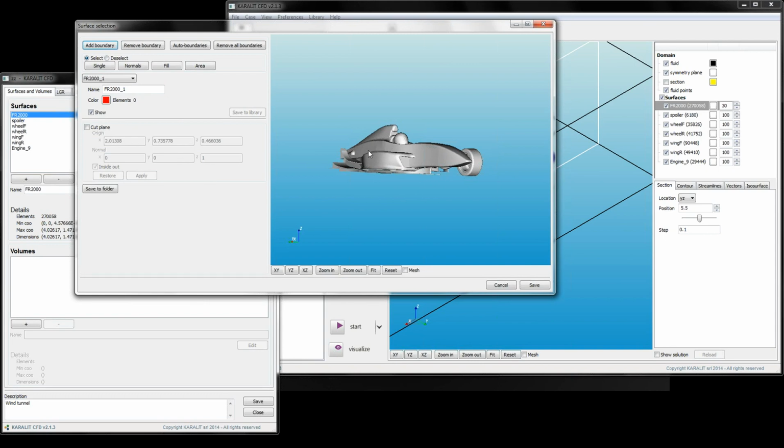The point being that we are tying the ventilation around the engine to the external aerodynamics instead of applying boundary conditions, which one would be uncertain of at that phase. It allows you to pick surfaces with various features here. I'm going to use the normals feature, and pick up that surface.